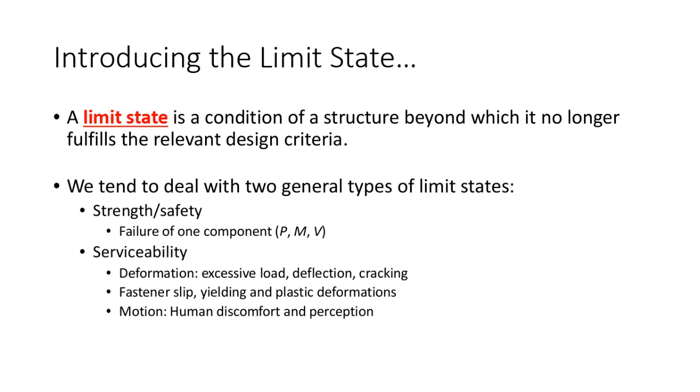So we take the length of the beam, we divide it by 360, and we say that's the maximum deflection. Now, let's say it's a wooden joist. If that wooden joist deflects more than L/360, it does not mean that the beam is going to fall down and kill somebody. That's not what that means. Where did that L over 360 come from? If the beam deflects more than L over 360, you'll start to crack the plaster.